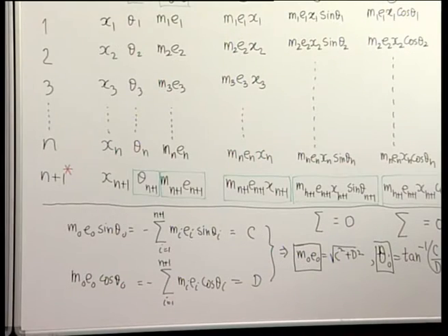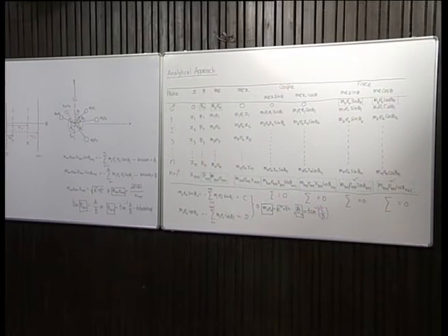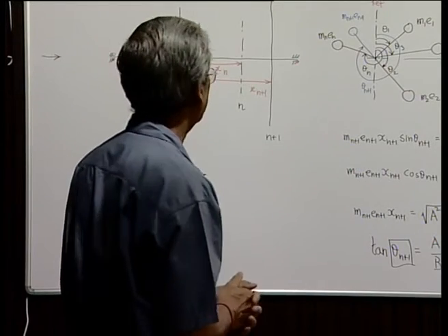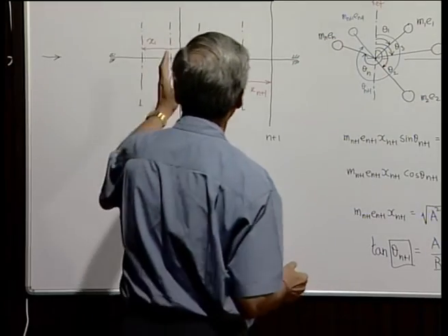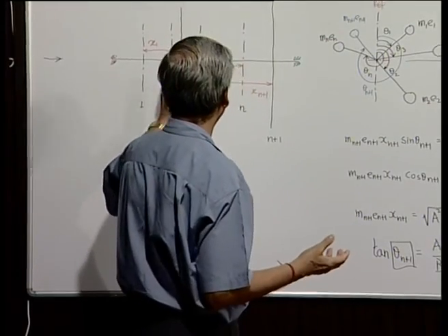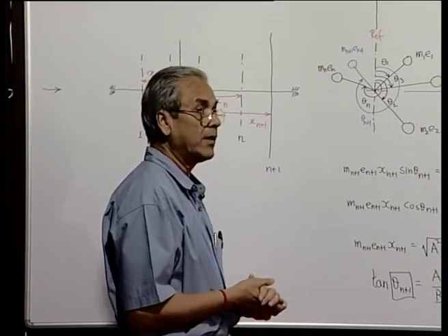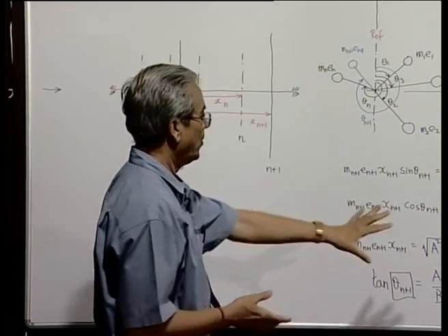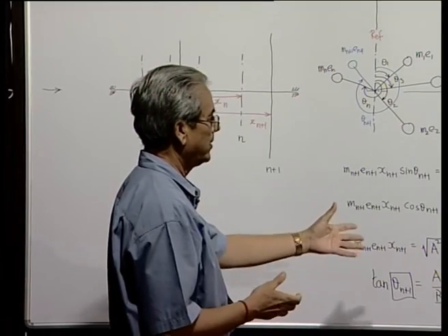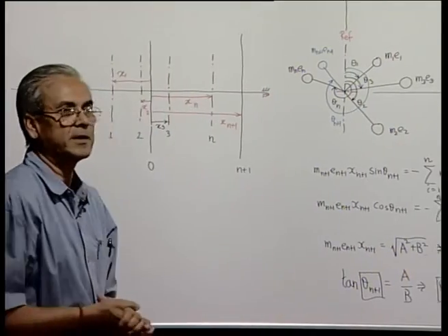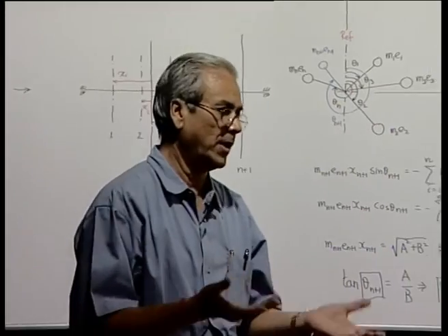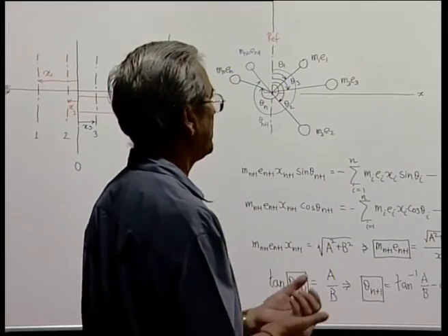So, you can see that following an analytical procedure explained in the form of a table, we can find out the 4 unknown quantities, that is the magnitudes of the balancing amount to be placed in the two balancing planes and their relative angular positions. They are all found out in this manner, and here obviously the answers will be more accurate, because we have followed an analytical procedure.